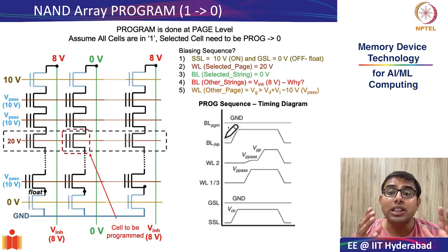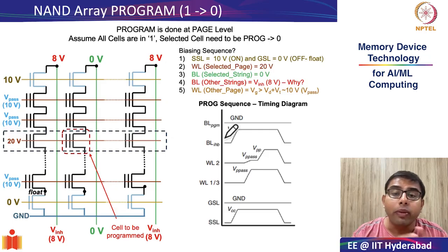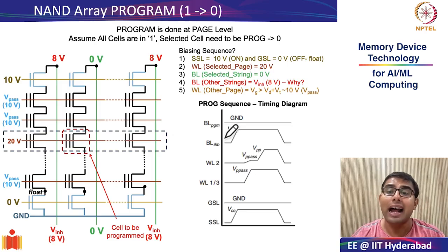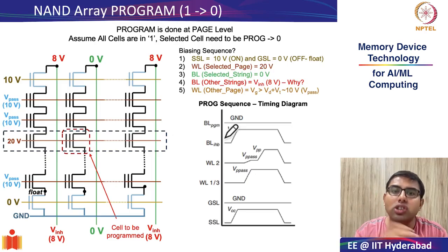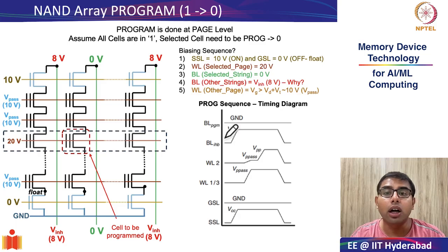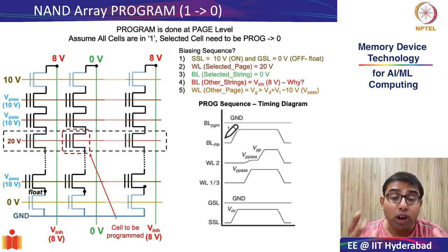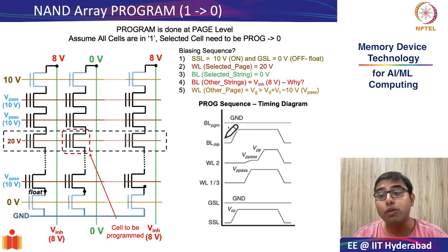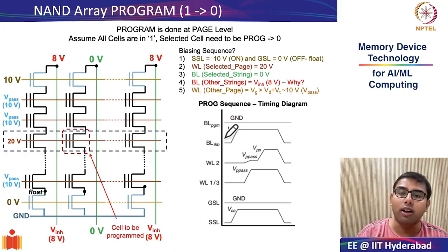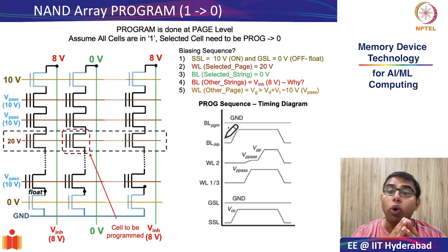This is the tunneling which happens through a triangular barrier at sufficiently high gate bias at the control gate of your flash cell. This transport mechanism gave us several advantages such as non-volatile operation both at hold and at read condition, but it also resulted in large biasing requirements and slow program times.